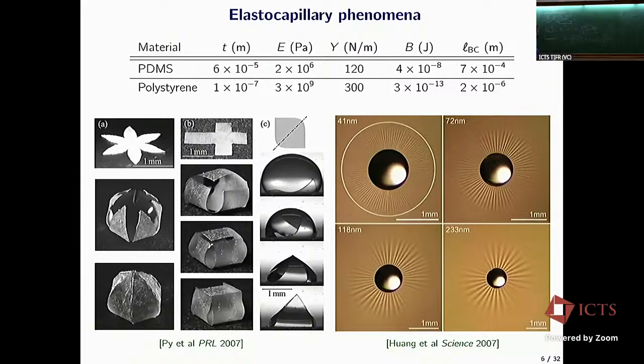So if I look at the effective strain, which is this difference divided by L, so L naught minus L divided by L, or by L naught, which is the same to the lowest order, this is of the order of zeta prime squared, and zeta prime squared is A squared over lambda squared. So this is epsilon. This we will use a lot.